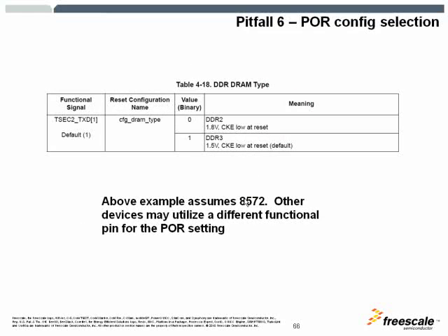The other important feature, again, to re-emphasize what was discussed previously: for DDRs, there's a selection between DDR types. That is a pin that needs to be configured on the board during power on, when the board is being powered on. So make sure that that pin has been brought up and proper pull up and pull down is applied.